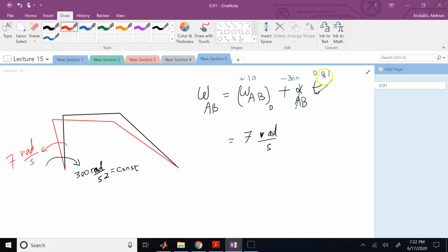So here you have a camera that can capture 100 frames per second. So every 10 milliseconds you have 1 frame. So you're going to get this red configuration. So that is your omega, this is your alpha. Clearly your angles would change. The R of B with respect to A, C with respect to B, and C with respect to D are not simply 2i, 2j, and negative 2i plus 2j. Now you have some angles. So you have to calculate these angles and then find this unit vector.